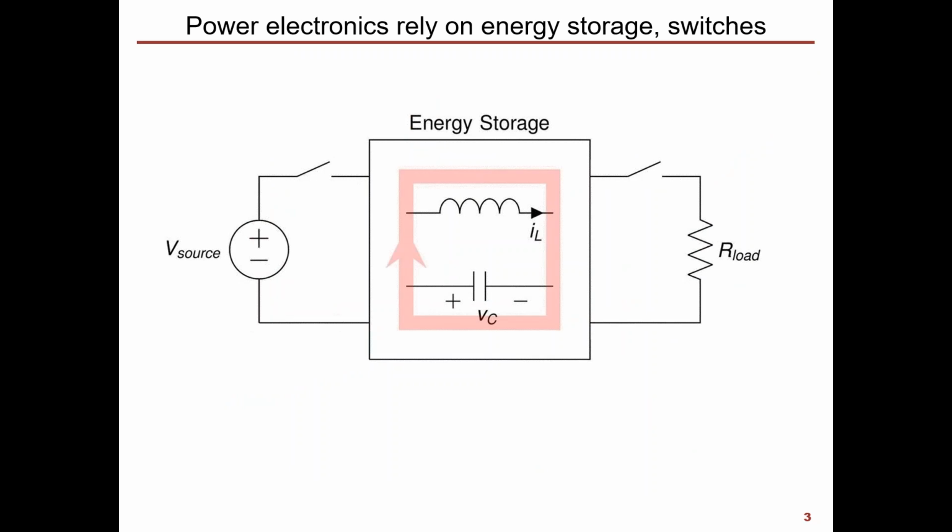Okay, perfect. Now, I imagine most of you are familiar with the concept of a power converter, but I'd like to briefly review it because it motivates a lot of the reason why we do this work. At its root, a power converter pulls energy in from a source. It momentarily stores it in some sort of energy storage, and then it delivers it to a load, typically in a different voltage or a different form. Now we control this process with switches, and it's cyclical, so we do it thousands or even millions of times per second.